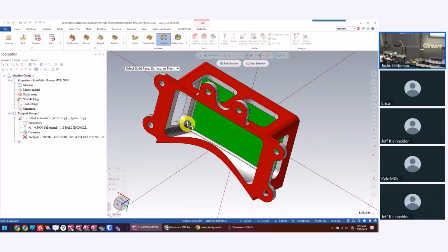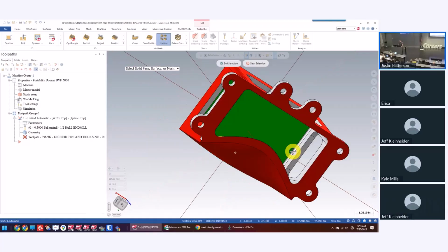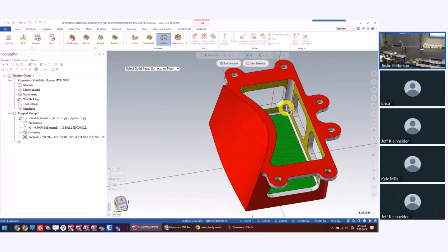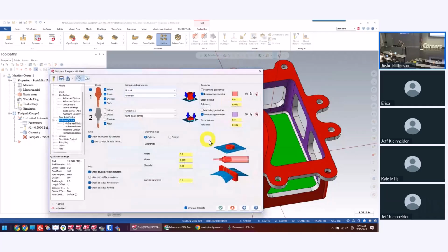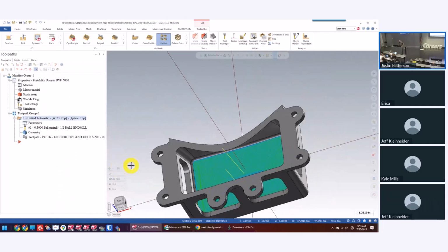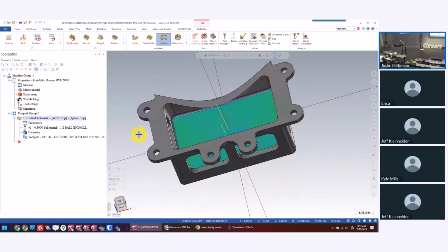I don't want the bottom radiuses or anything like that because I'm using a .250 or a 1/2 inch ball nose, and that's a 1/8 inch radius there in the corner, okay? So we go just like that. Retract the tool to the cut center of the part. There you go. Look how much that cleaned that toolpath up. We just turned this into a really nice looking 5-axis toolpath by simply using collision control.